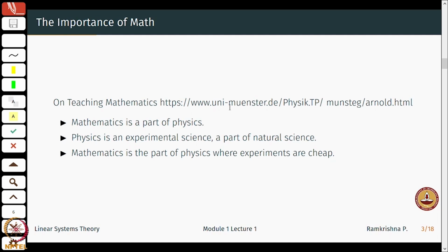Once I get the equivalent circuit parameters, the circuit model, then I can run whatever experiments just by using standard circuit theory. For example, what could be the efficiency of a transformer which is operating on a load of power factor 0.6, and so on. For all those things, I don't really need to buy a transformer, run through experiments and get my result.